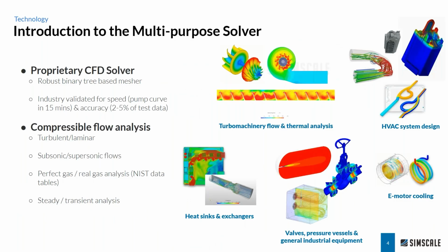Getting a little bit into the topic, the solver that we are going to be demonstrating today is a proprietary CFD solver called Multipurpose. It is based on a binary tree-based mesh, which is quite robust and able to handle quite complex geometries with very minimal cleanup. It is a finite volume-based RANS solver, and it has been very widely validated for industry applications, both internally at SimScale and by a lot of our customers, as you can see in the testimonials page on our website.